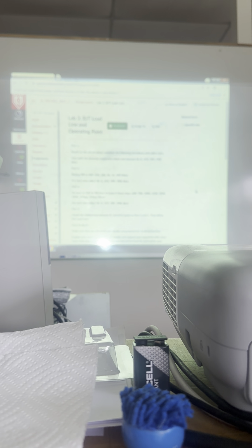Here's what's going to happen. Let's say you're at 50K. With RB at 50K, you end up here with a specific IB. You with me so far? So I'm here, I have a VCE and IC when RB equals 50 kilo ohm. What's going to happen when I increase or decrease RB, when I'm playing with IB? That means I'm moving up the line or going down the line. That's all. Does that make sense?